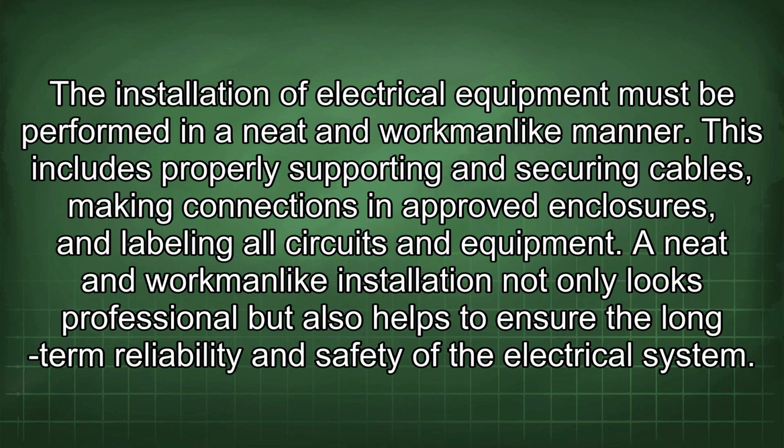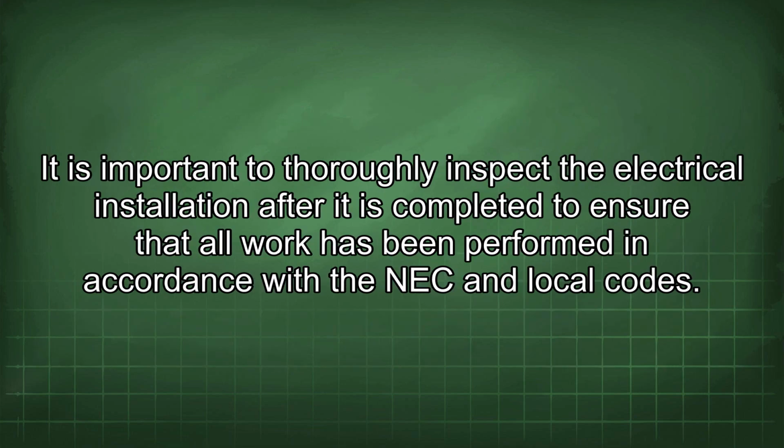The installation of electrical equipment must be performed in a neat and workmanlike manner. This includes properly supporting and securing cables, making connections in approved enclosures, and labeling all circuits and equipment. A neat and workmanlike installation not only looks professional but also helps to ensure the long-term reliability and safety of the electrical system. It is important to thoroughly inspect the electrical installation after it is completed to ensure that all work has been performed in accordance with the NEC and local codes.